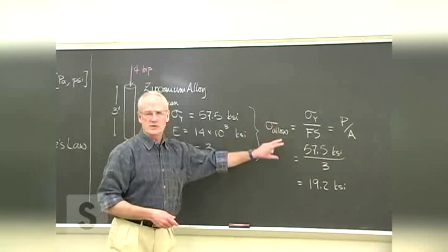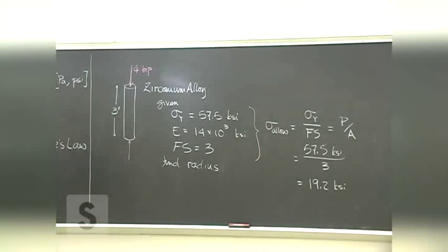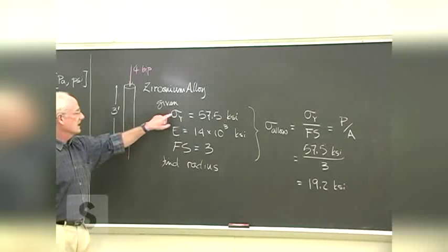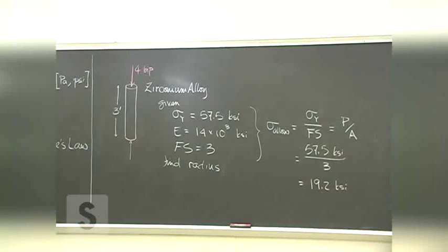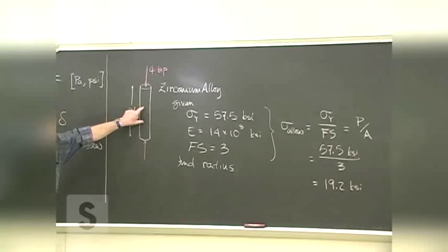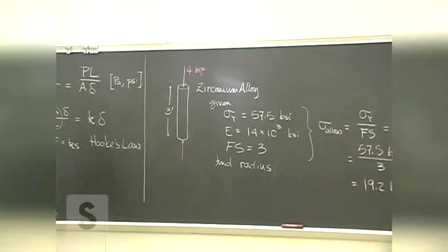But that allows a lot of margin for miscalculations, assumptions, or maybe even experimental differences in what the yield stress really is. So typically we don't design very, very important pieces like structural members in nuclear power plants right to the limit. Put a big factor of safety on.